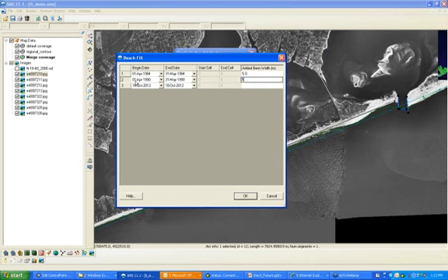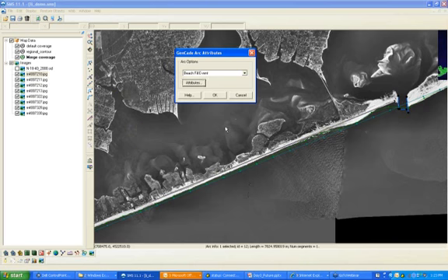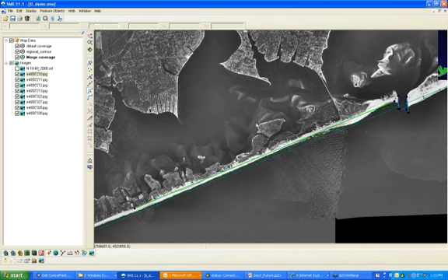And then it would be the same added berm width, although you can enter different berm widths regardless, even in the same beach fill event. I'll click OK, and OK again. And now it's going to turn green. So that's as far as we got yesterday.